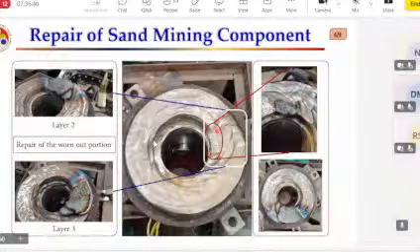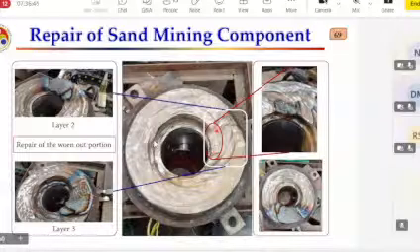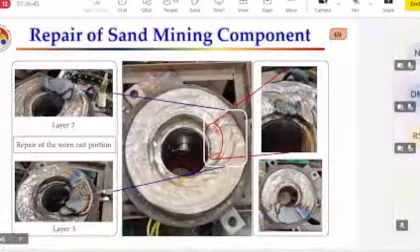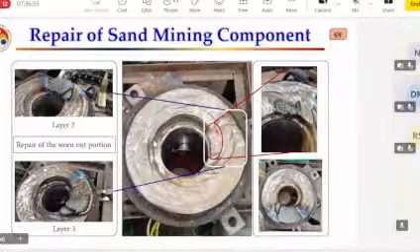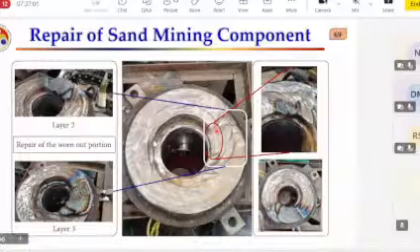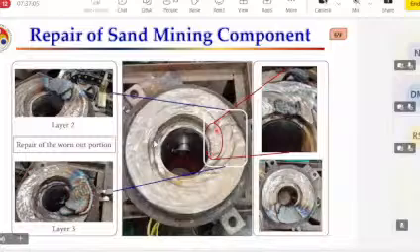And yeah, if we compare the continuous deposition, you can see there's much more warpage because of continuous deposition. But with these new strategies, we can reduce this warpage as well. You can even come up with some other ideas also. Right now we're going continuous, but we can use some ordered way, which may even reduce warpage further. So these kinds of new strategies,